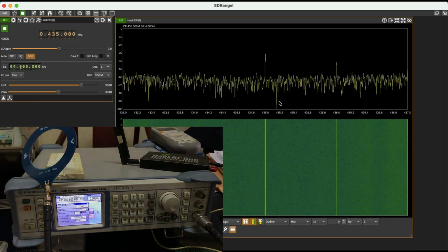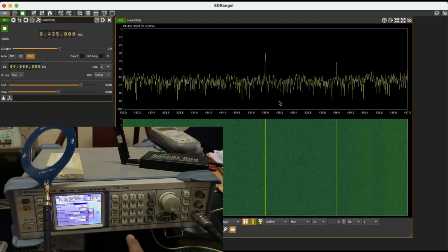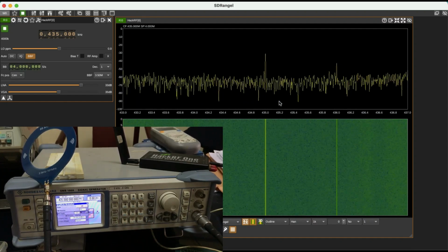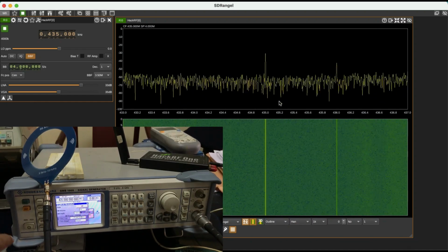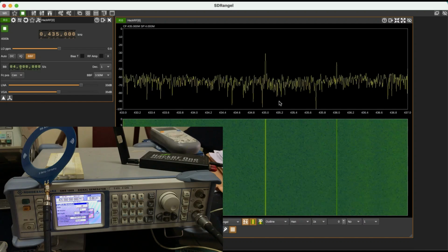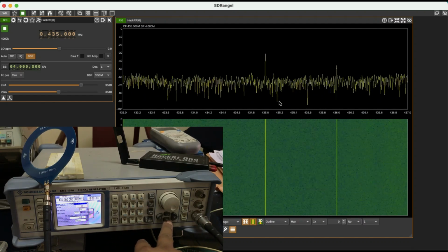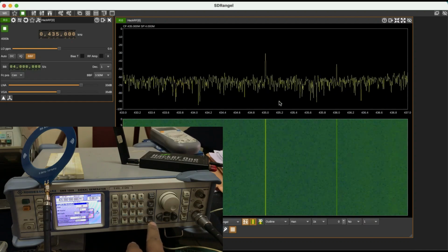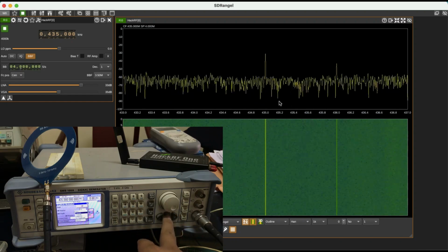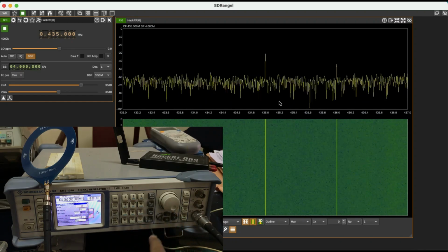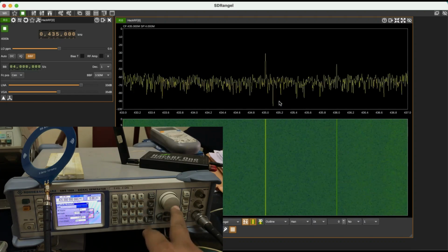Next step I need to do is go ahead and change this modulation depth to about 100%. All right, and let's change the source because 20 kilohertz is a very small signal to be modulated at 435 megahertz. So I'm going to choose this to be around the maximum possible range, which is about 1 megahertz. And I'm going to first do the modulation using an analog signal. So I'm going to assign a sinusoidal wave, and I'm going to turn on my modulation.